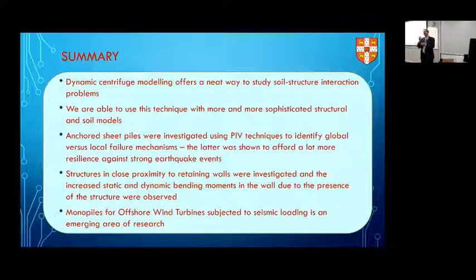Also, where you have combined effects, like, for example, seepage, consolidation, and heat all happening, which is the real field case, then obviously we need to go to the centrifuge to do that. Okay, the scaling law works pretty much like how the scaling law works for the consolidation I explained earlier. Thank you.